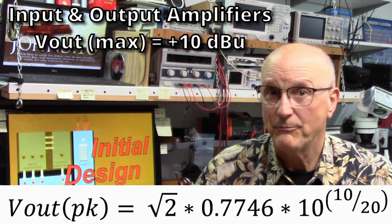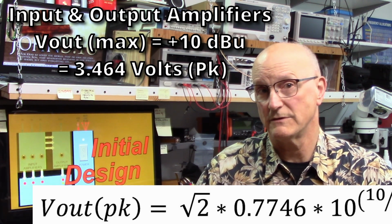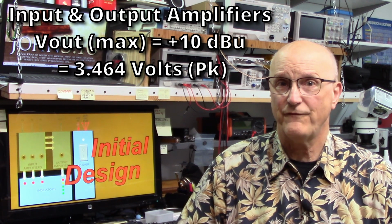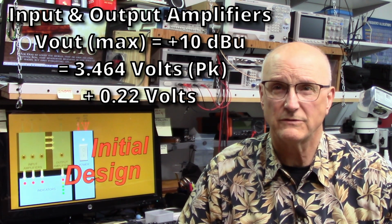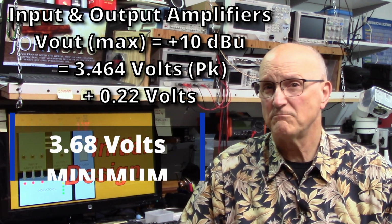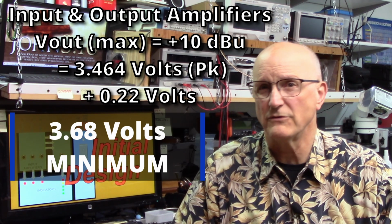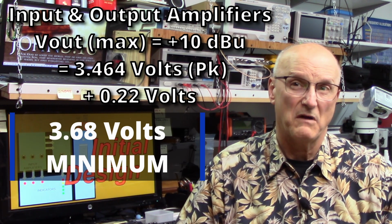Doing the math, the peak voltage amounts to 3.464 volts. We figure in the fact that the chosen op amps need at least 0.22 volts of headroom. Our power supply has to be no less than 3.68 volts. So based on this alone, 5 volts seems sufficient.